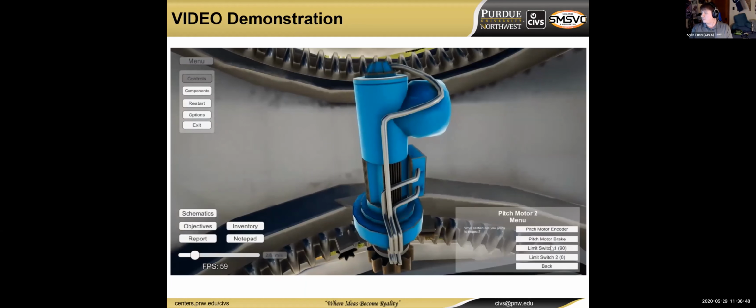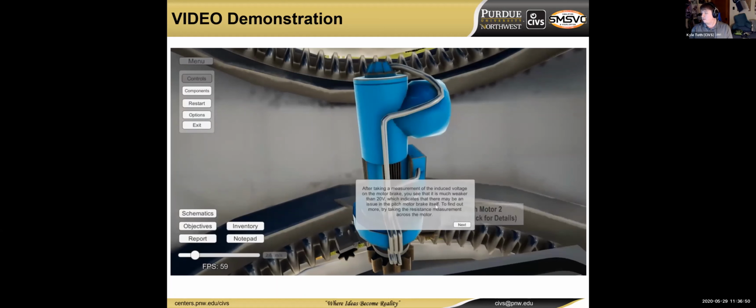And so now that we're able to do that, we're going to get to this third one. We're going to check voltage, and it's going to tell us that the voltage isn't what it's rated to be in a stop mode. So now it's going to tell us, hey, this might indicate that there's a problem. We should also check to see what the resistance is.